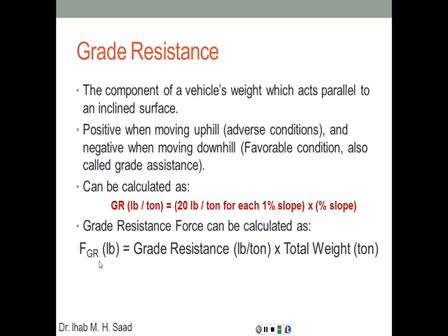So the grade resistance force is equal to the grade resistance, the factor that we calculated from here, times the total weight of the equipment in tons. Again, in this case, the issue of whether the equipment is loaded or unloaded is going to make a big difference.